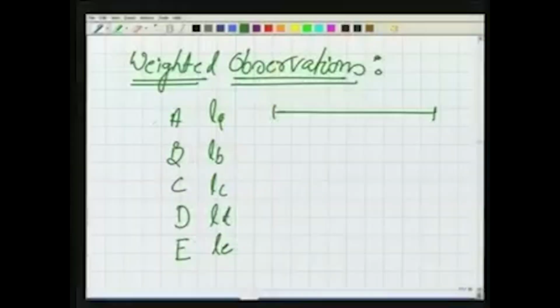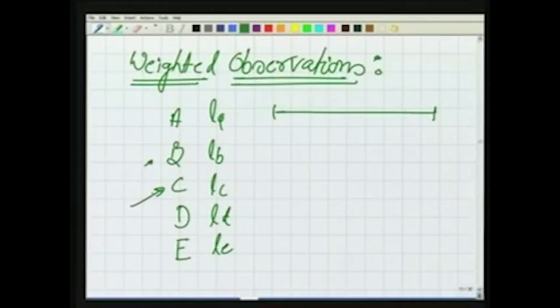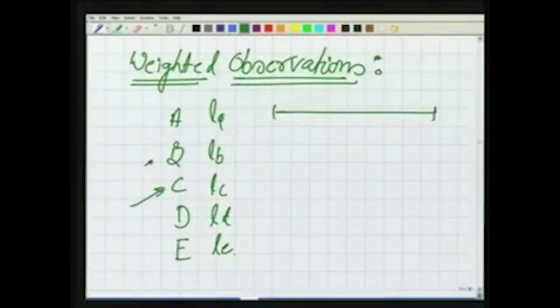Person A looks at the instrument in a slightly parallax way. It doesn't look exactly the way the instrument should be read. Person B, maybe he is committing some blunder there. While person C is working, the temperature is more. There is some error in the instrument. Okay, it may be the systematic error. Even the way you put the instrument in the ground in order to measure the length, slight changes are there. What we saw earlier, we can never measure the true value. Only if we can measure the true value, will all these observations be the same.